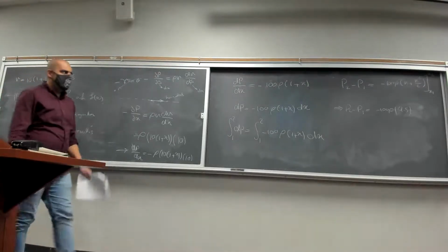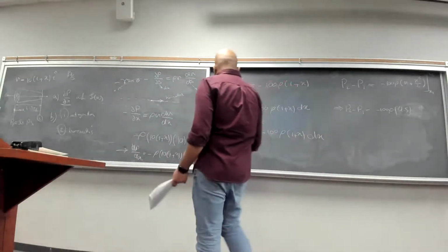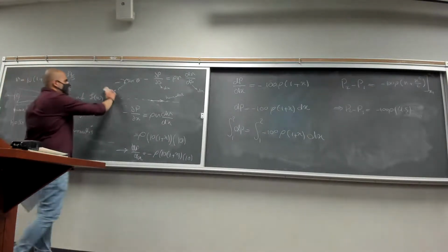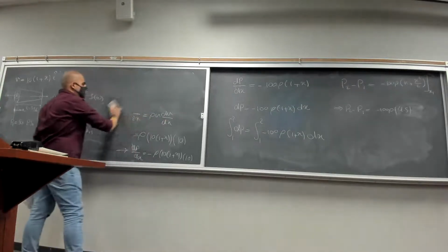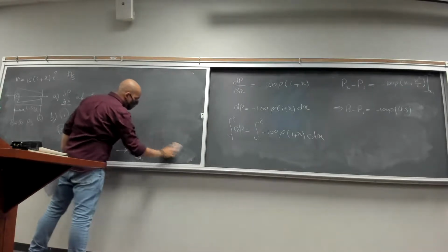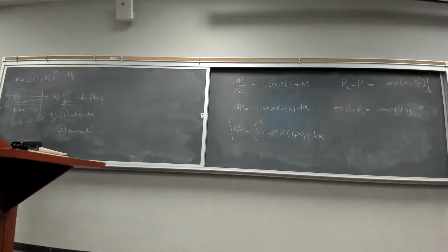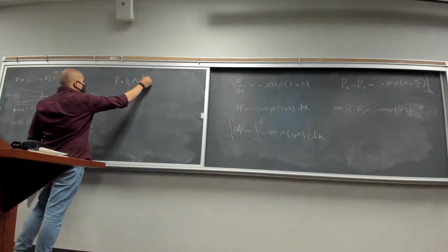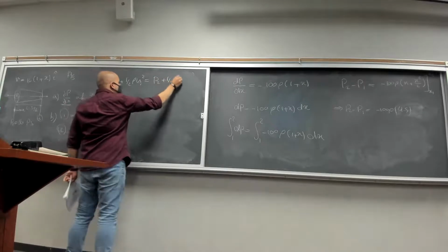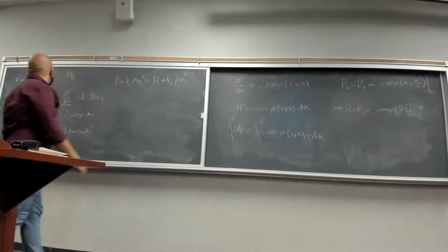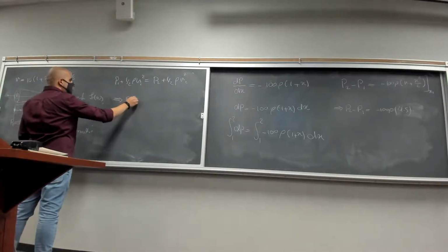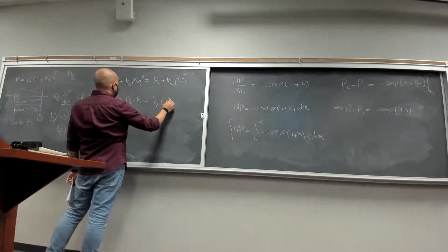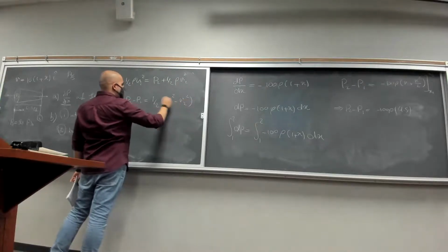This is through integration. I don't want to give you the final value because that doesn't really prove anything to us, because we are not going to calculate it, right? As long as we get to the same expression, we are proving that the Bernoulli equation and this integration are going to give us the same value, right? So Bernoulli's: P1 plus 1/2 rho V1 squared is equal to P2 plus 1/2 rho V2 squared. Okay. So P1 minus P2 is going to be equal to 1/2 rho times V2 squared minus V1 squared, right? There's also a rho here.